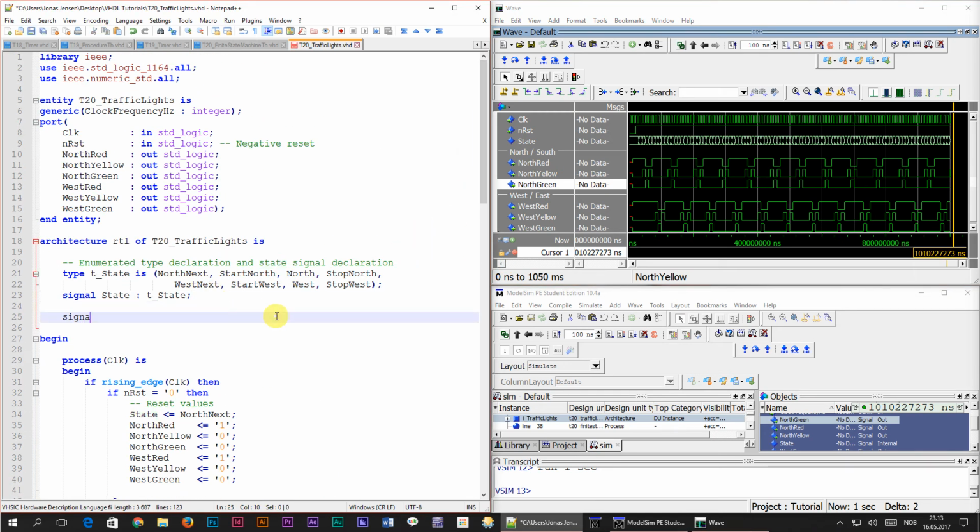Here we're going to declare a new signal with the name counter of type integer. We're going to use this signal for counting clock periods. I could leave it like this, but this time I'm not going to. It's good practice to define the range of the integer signals. This is a way to tell the compiler how many bits it needs to reserve for implementing this signal in hardware. After the range keyword we type 0, 2, meaning that the lowest value this signal can represent is 0.